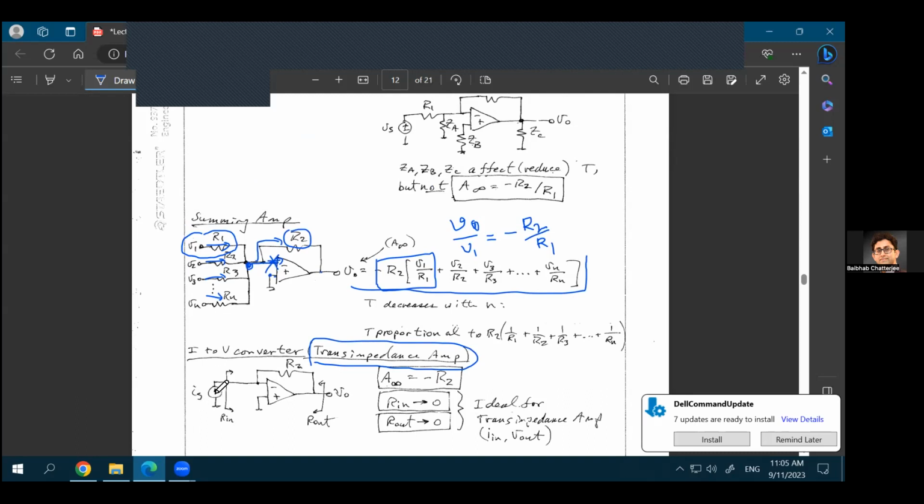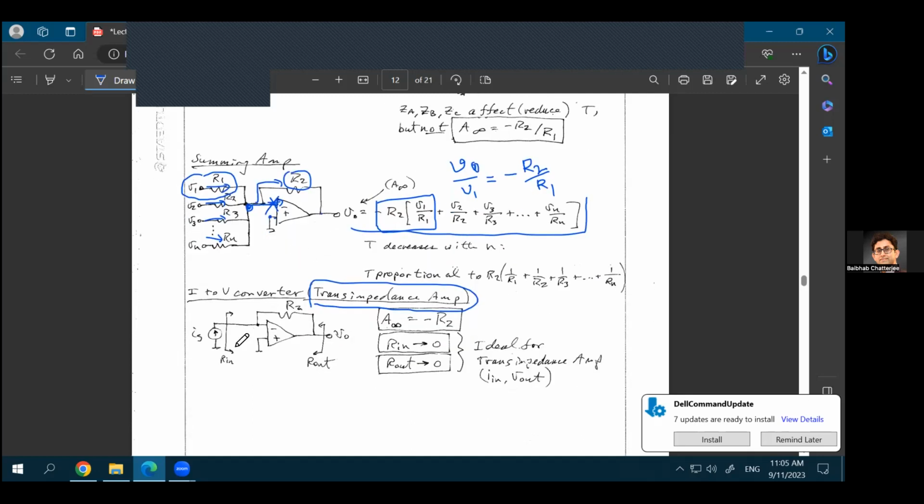So it's the Ohm's law equivalent of the previous non-inverting amplifier circuit. That instead of applying a voltage at the input, you're applying a current at the input. So you don't want that resistance anymore because you already have it in the form of a current, and that current will entirely flow through the R2 resistance. What would be the gain of this circuit?